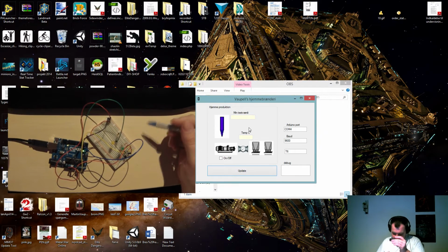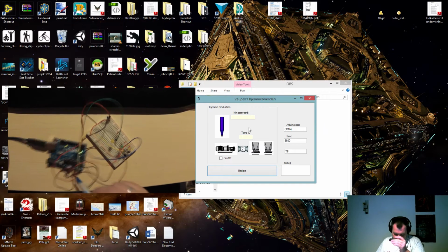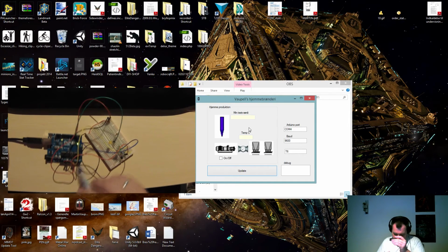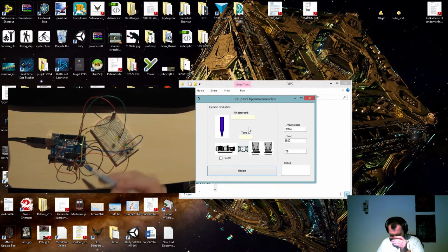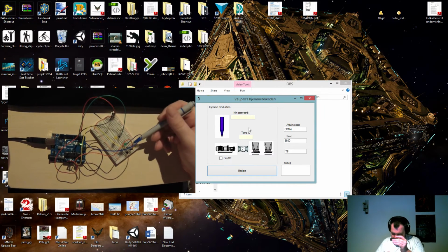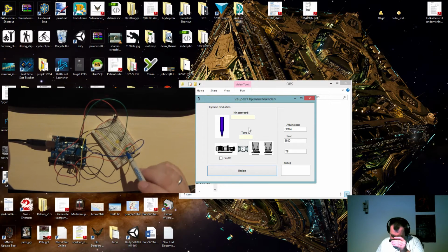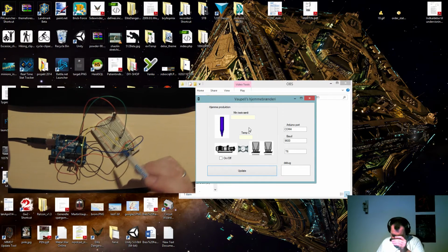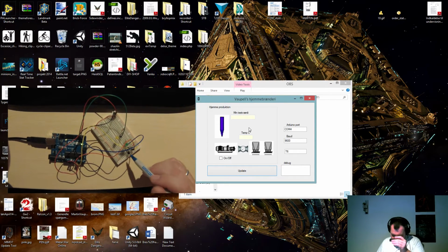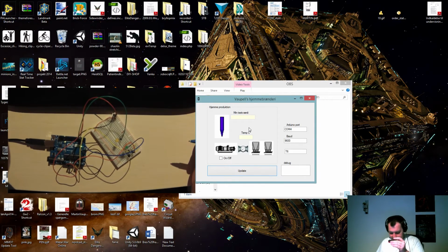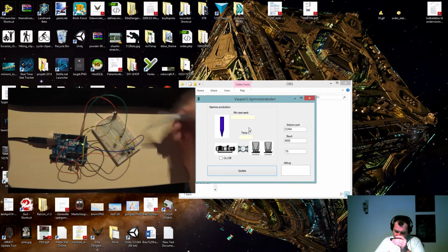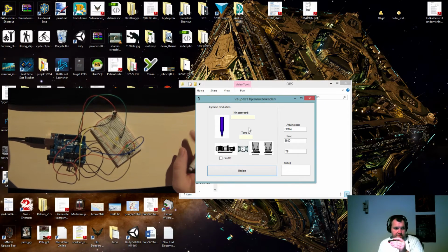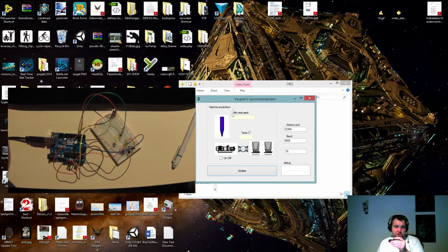And it's just hooked up to ground right here. I'm measuring at 2 points, as you can see, analog 0 and analog 1. The yellow wire measures, let's see, the light sensor, and the orange wire measures the temperature. These two over here are just sending power to the LEDs if they are supposed to be turned on. Okay, now let's watch the screen.